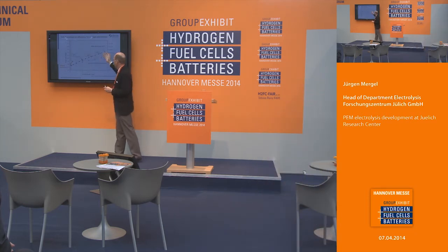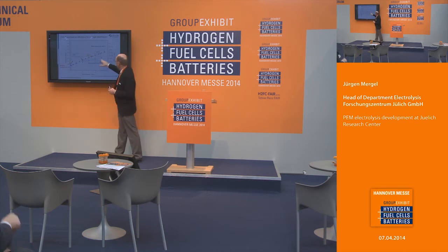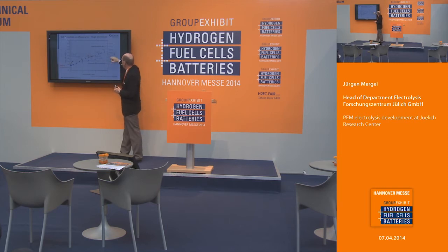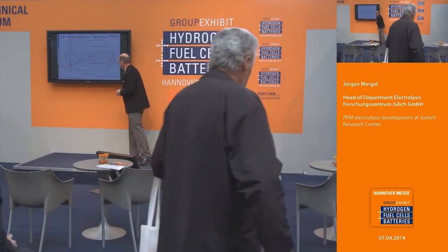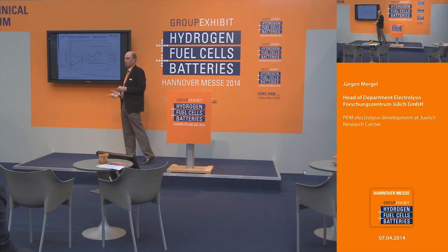If you look, they called it GINA as an advanced PEM electrolysis unit. This was presented at the last DOE meeting in 2013. Then you can see at 300% overload, if you run this at 2 amps per square centimeter, the efficiency is greater than 70%. And this was for us the motivation to go into PEM electrolysis.